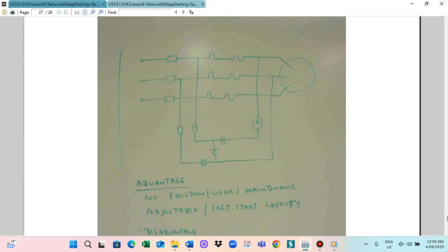So this is my experience with a mechanical brake system. When running a mechanical brake system, sometimes the brake will not release because the control system may malfunction or disconnect. Due to this, the motor will overheat. If you continue to run, finally the brake will melt down and the motor can also burn.